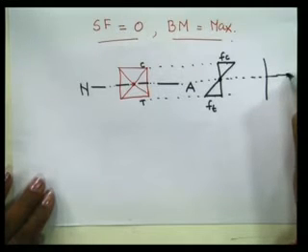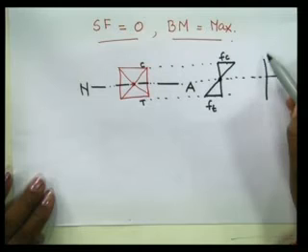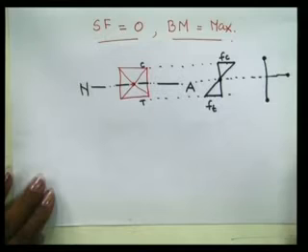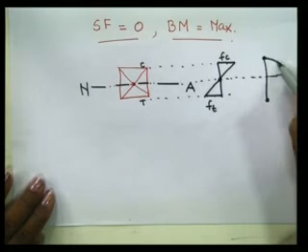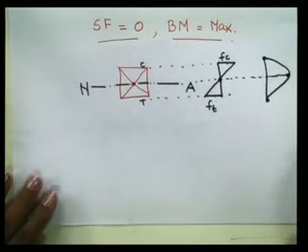Maximum, right? Similarly, where the bending moment value is maximum, shear stress value will be what? 0. So at the top and bottom the shear stress value is 0, and at the center where the bending stress is 0, the shear stress value will be maximum, right?